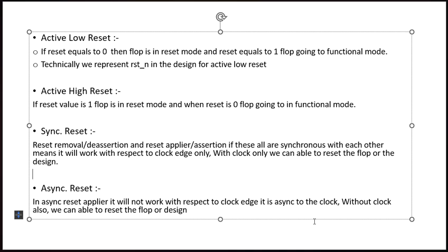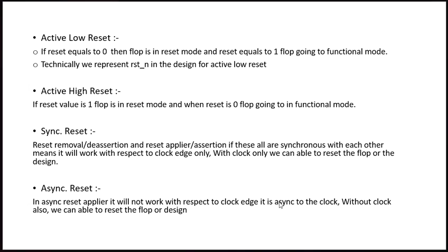This is the main thing in asynchronous reset. So these are the definitions for synchronous and asynchronous reset. In synchronous reset, reset removal or deassertion and reset apply or assertion are all synchronous with the clock edge. But in asynchronous, reset apply is not synchronous with the clock edge. This is the main difference.